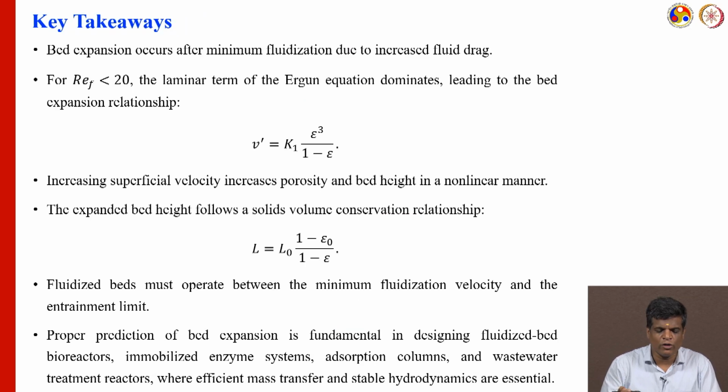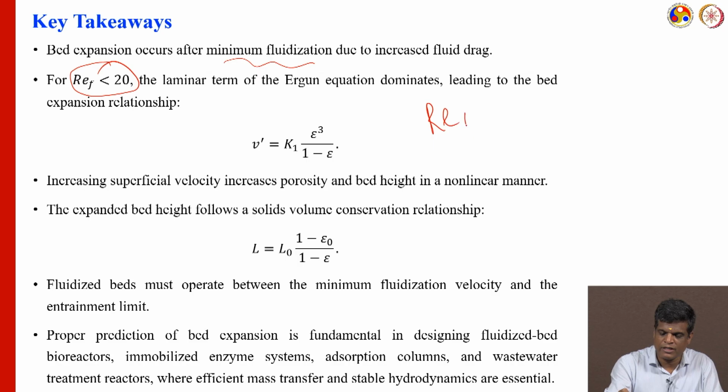The key takeaway is that bed expansion definitely occurs once minimum fluidization is reached, because of the increased fluid drag. We write REF for the Reynolds number of fluidization.